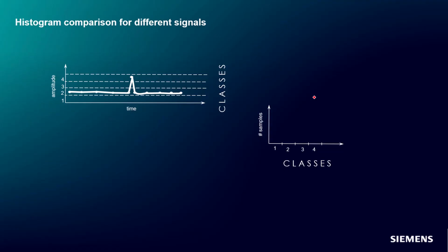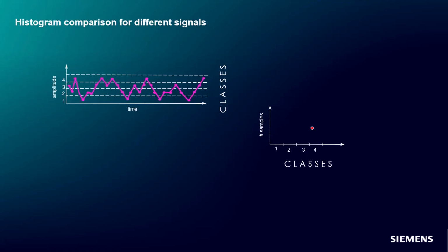Now let's look at where we have something that looks like an impact, something that's really sharp and peaky, but then dies out quickly with time. So I have 0 for my first bin, a high concentration of data points in my second bin, 0 in my third bin, and a single data point in my fourth bin. So I end up with something that's very peaky in shape, that's not normally distributed, that has a lot of skewedness to it, which is essentially what kurtosis is doing. It's kind of telling us how skewed our shape data is.